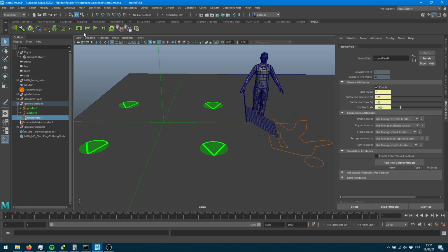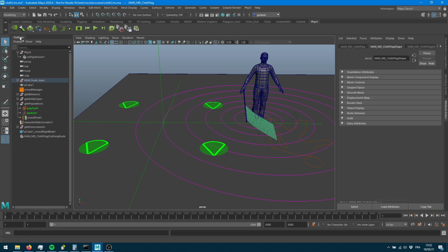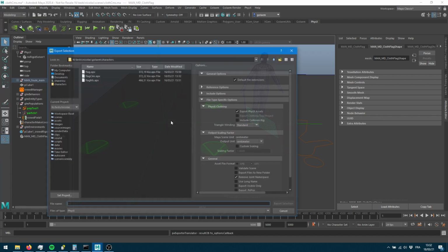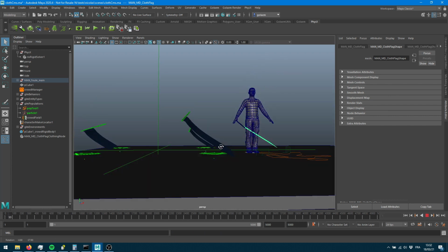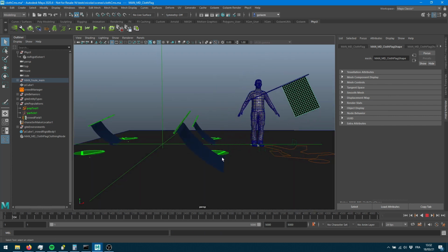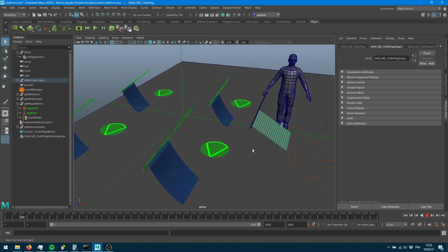And if I want to make sure that I'm using the right stuff, I can put something really high in terms of maybe damping. Let's see how it looks if we do this. So okay, we've got a really high damping here. The character is kind of slowed down. So let's go back to the initial frame. Export selection once again. Override this. And see if we've got a similar simulation. Now we've got really high damping on our Golem clothes. And yeah, it's following the same parameters as the ones you've been injecting.